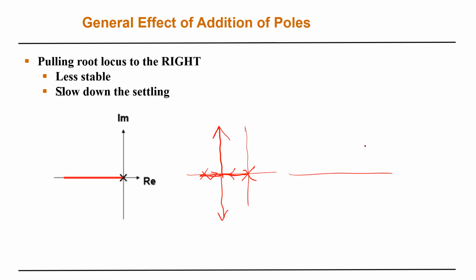Yes, between the two poles we'll have something like this. It will go to infinity, and it will go to infinity vertically. Now suppose I add one more. This is the original; let me add two. How does this look now? It's asymptotic. Those will approach each other, and then they break, and they will go like this. So the system becomes unstable a little bit later. If you calculate the asymptote, you will see that the angle will be 60 degrees. That's why it will go in that direction.